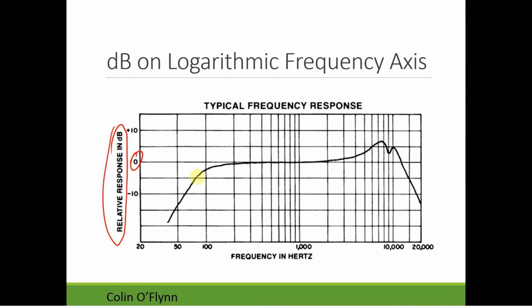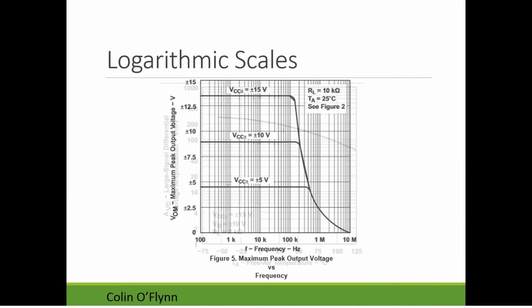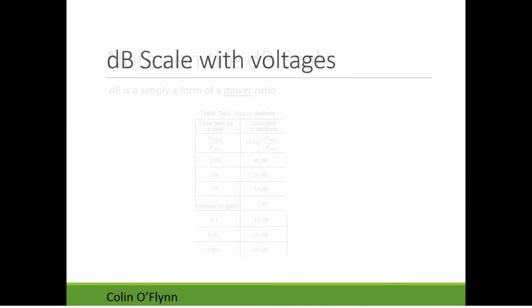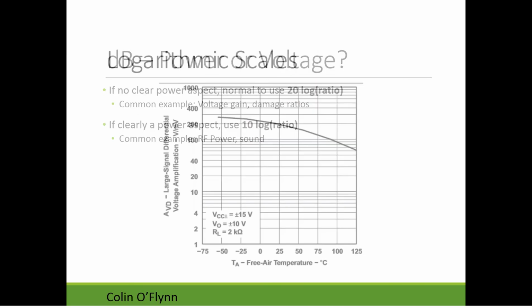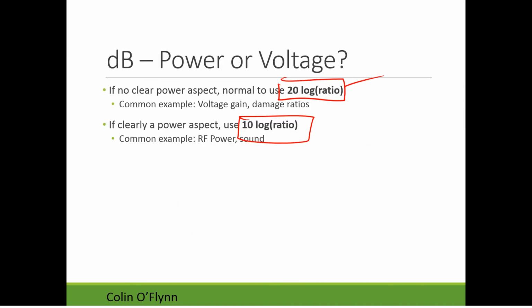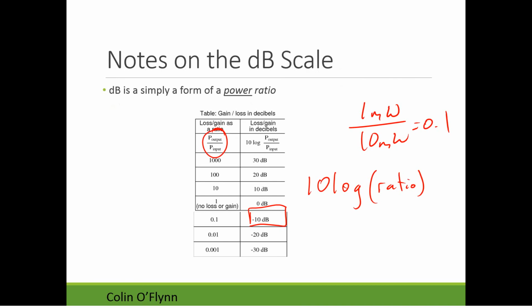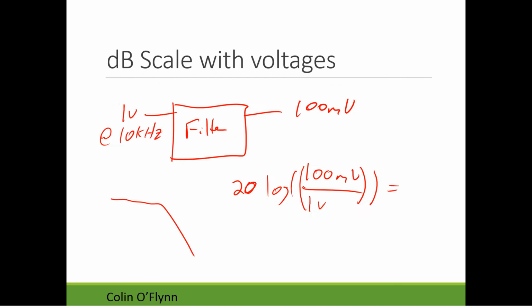And again, it doesn't show it in a logarithmic scale, but because it's in decibels, it's a logarithmic interpretation. So minus 10 dB really means, if you go back to our little graph here, a 0.1 change in the power: it's 1/10 of the input power at the output. So it quickly falls off. And if you go up to 20 or 30 dB, negative 30 dB is 1/100th of the input power at the output.